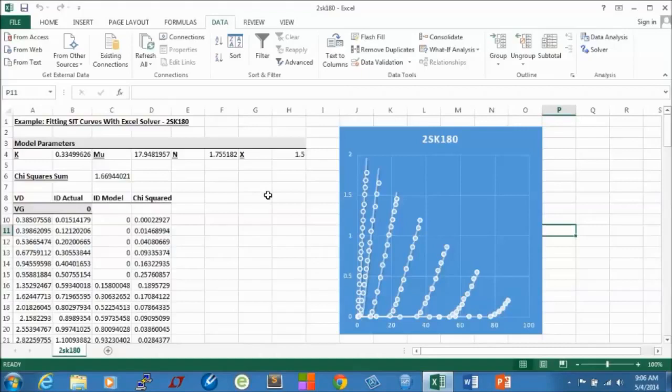I should mention that when you're fitting curves and working on these models, if you need to prioritize, then you want the curves to fit best where you're going to use the model. So if the operating point for your circuit is going to be 50 volts and 1 amp, then you want the model to fit closest in that region, and maybe it doesn't matter so much what it looks like at 0 gate voltage or whatever.